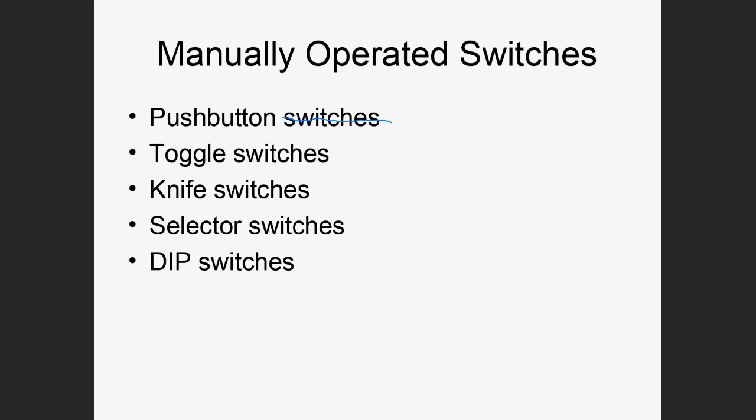They're usually numbered. And in the garage door opener, they use those to code the transmitter and receiver to the motor. You can actually go in and set the code. So if you ever had to do that before, that's a dip switch, dual inline package. If you've never done that before, I guess these are really not that important, because typically you don't see these with PLCs unless you have some kind of special application that I'm not aware of.